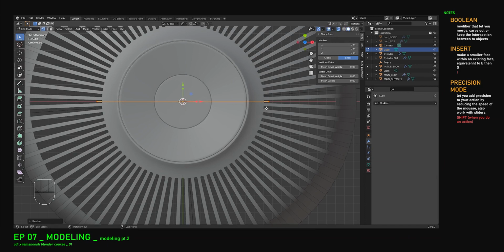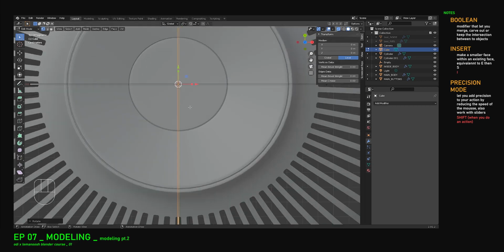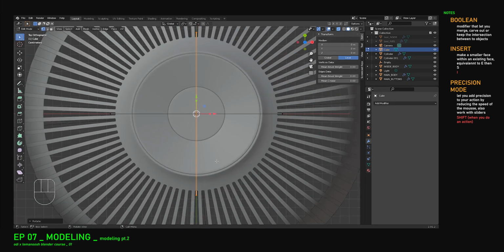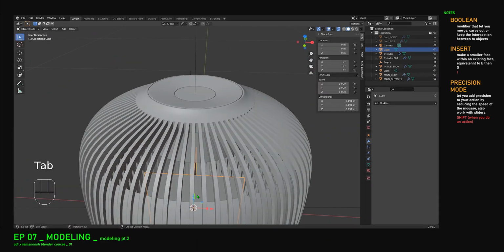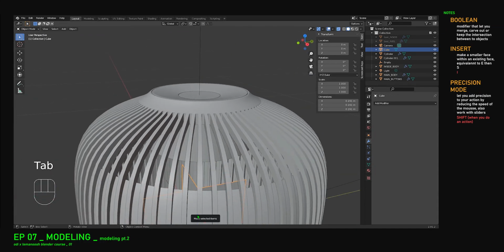Something like that. Duplicate the geometry in edit mode. So Shift D, right click to leave it in the original position, and R for rotation and 90 degree. You can just input values by writing them down while you're doing it. So if I want 10 degree of rotation, I do R and press 10 then. But so here it's 90 degree. So we have this cross.